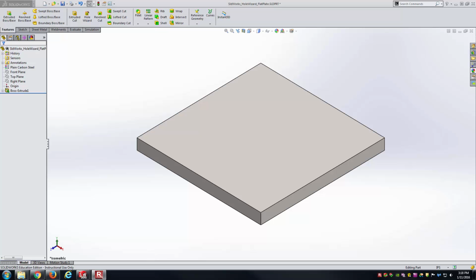holes. Also if you're going to create internal threads in your holes, and so you've got a hole that's going to be threaded, you're going to eventually pass a fastener like a bolt down into it, and you want to be able to specify in that hole what actual type of thread it's going to have. And so you might have a quarter 20, half 20, and so forth there, and have that information described within